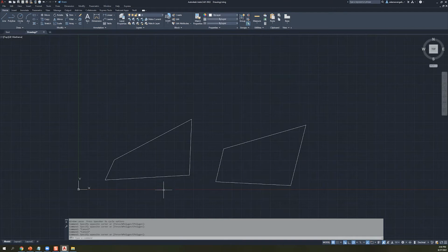Again, it comes into play for a variety of different commands and different functions, but ultimately you just need to know with confidence that you're placing a line at the place where it needs to be placed, right? And that transcends pretty much everything and kind of affects every command that you're going to be doing from here. So should you have object snaps toggled on? Yeah, absolutely, you should.